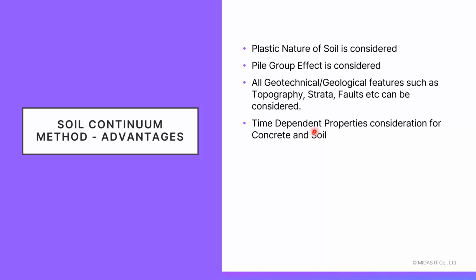Then the time dependent properties of the soil and concrete can also be considered. Let's say you're dealing with clayey soils and soft soils, and you want to consider the consolidation effect as well. You can run the consolidation analysis in the GTS NX software along with the loads that are coming from the structural team. And then you can understand with respect to time how the stiffness is changing as well. So this kind of time dependent calculation can also be done. This is one more advantage.